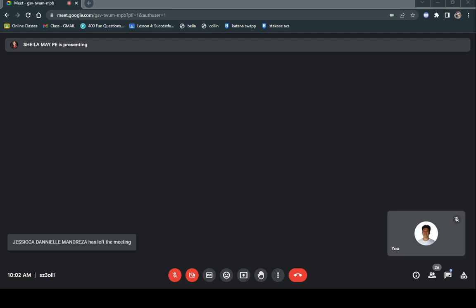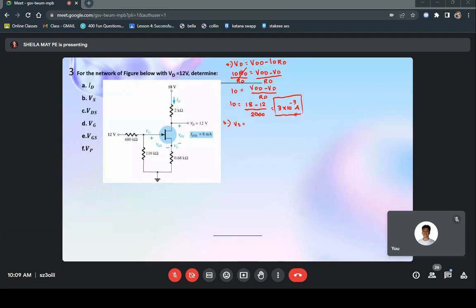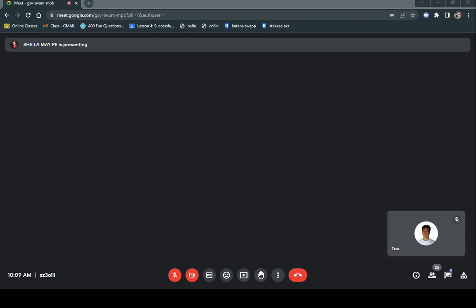So next, we need to find VS. ID is 3 milli, RS is 0.68. So VS is 2.04.